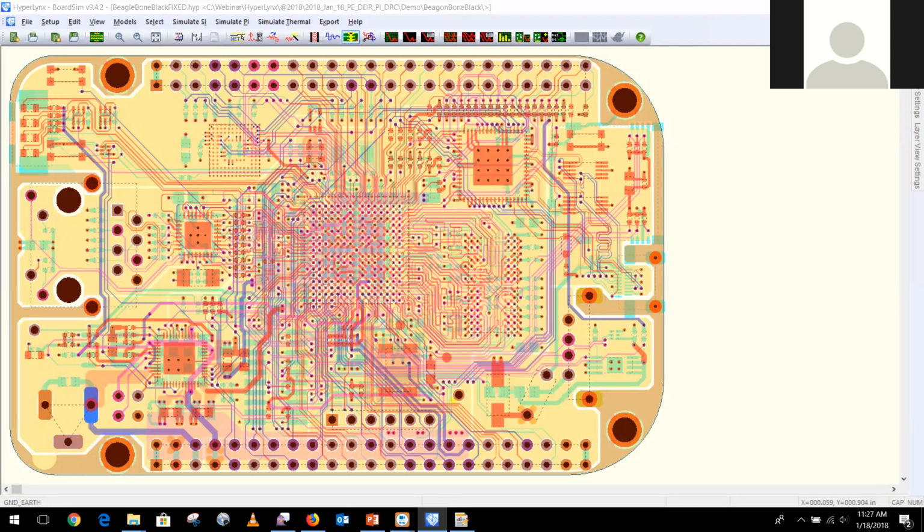So what you can do is define a group list. I just want ERC to check DDR signals only, only the signals that begin with DDR underscore asterisk. So all the DDR signals I check with this rule, and all the Ethernet signals I check with that rule. You can define a list and tell the tool to just run a subset of that list. So that hopefully answers your question of can we select only critical nets to check in the ERC? Yes, we can. Not just one critical net, we can define a group.